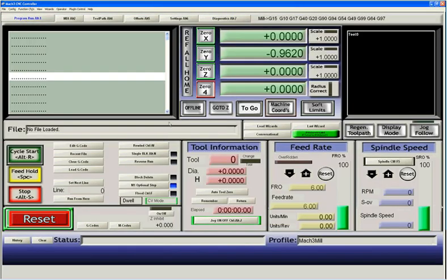That's it for the most common problems in getting Mach 3 to actually put out. A good way to check to see if your printer port is working is to use that auto pin input setup, because it will at least tell you if your printer port is working. If that routine works for you, your printer port is valid and your motor signals are likely going out, but your breakout board may be missensing the charge pump input, so you want to read the documentation on your breakout board to make sure that the charge pump is not your problem.